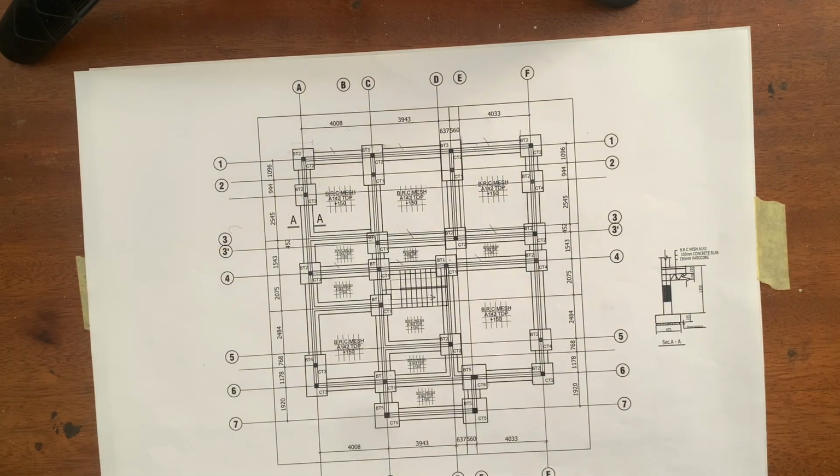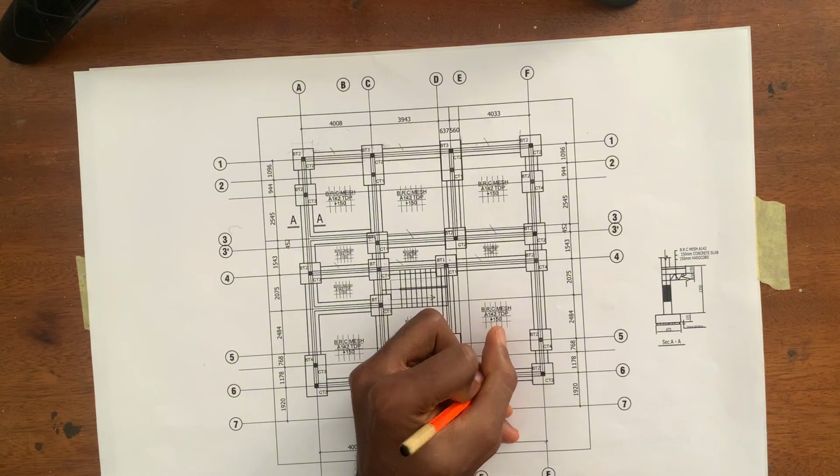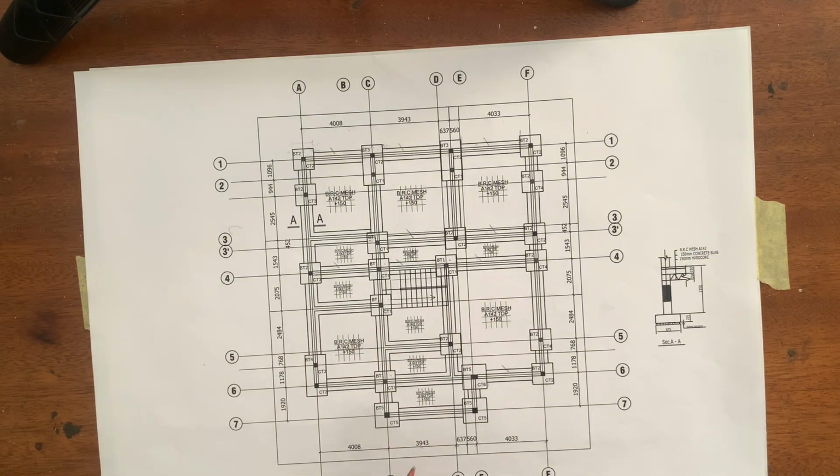So we've booked for this point. The next point we can now book for is this point here. I'm trying to do the easy ones before we get to the more complicated ones. So let's work on this one. Similarly, we know that from this midpoint here down to this midpoint here is given as 4,008. So if we minus half of the length of base type 4 and that of base type 1, we are going to get the dimension from here to here.